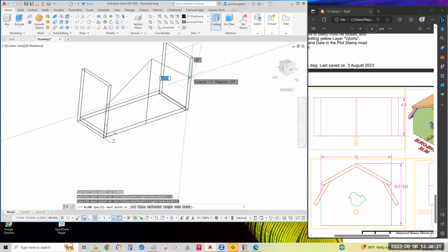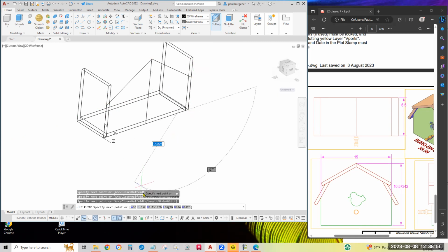I'll come all the way. Let me acquire that point. Come up there. 2 dotted lines with O-snap tracking guide me to 5 units up that right side board. Click, come down to endpoint and close.